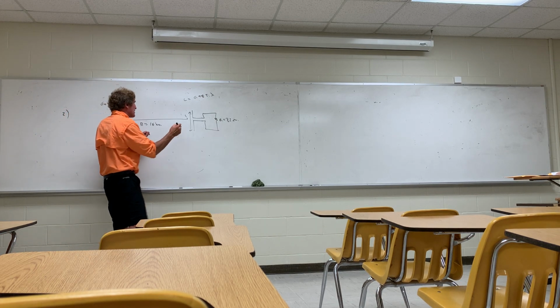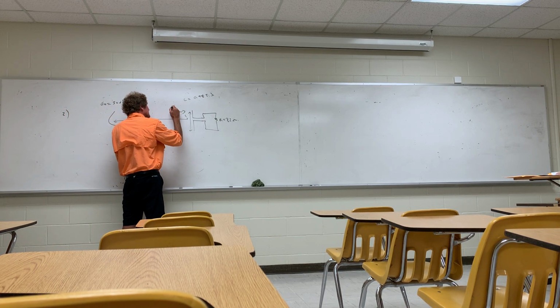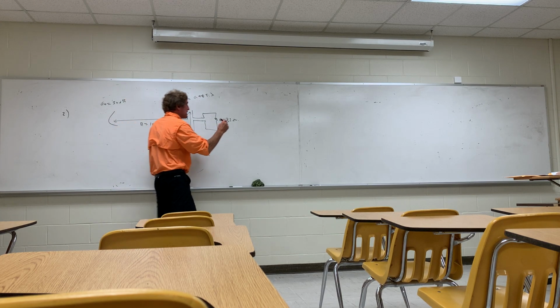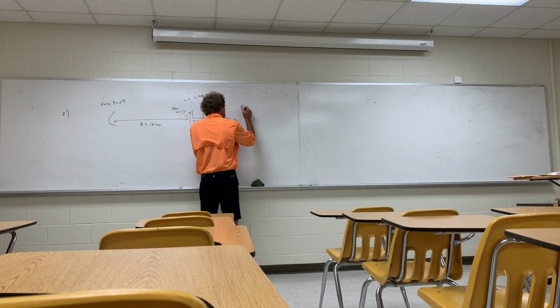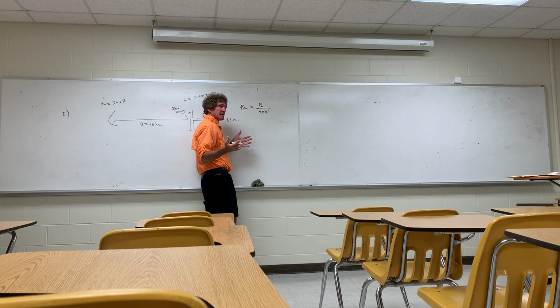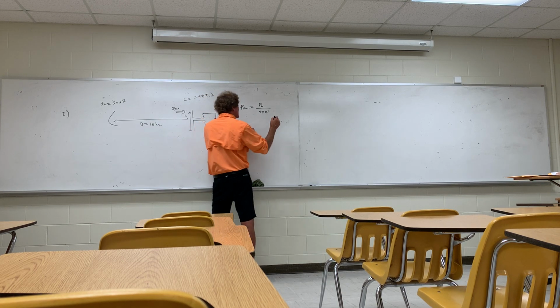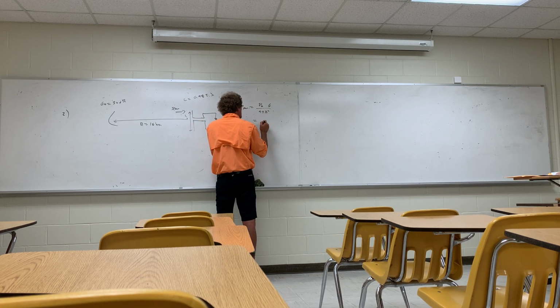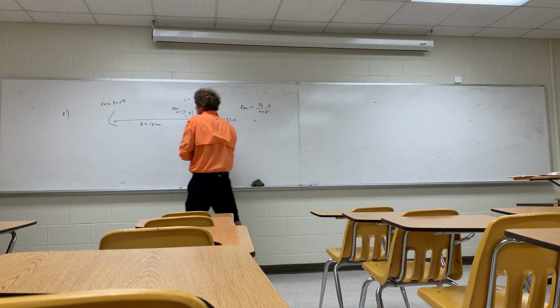antenna. So they want the power density right here. I want the power density right there, P average right there. And P average, always take the transmitted power over 4 pi R squared. That gives you the power density without any type of a gain enhancement, and times the gain. So transmitted power, let's put it here.